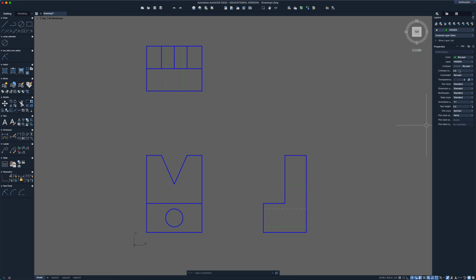And to do that, we're going to change over to the center layer. The scale right now says 5. I can just change that to 1, which was its default. And now if I come over to the left into our tool sets, you see it says dimension. There's this circle here and it's got the drop down list. So I'm going to hold and it says, hey, there's a center line. So I'm going to hover on that, release, and now it tells me to select the first line.